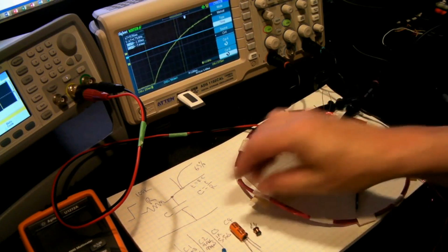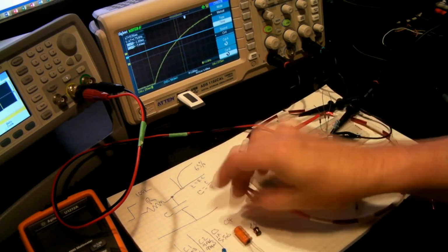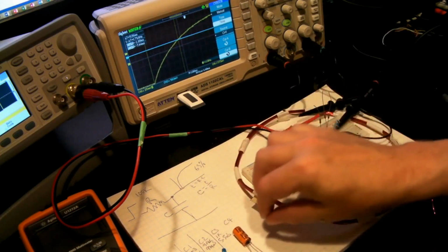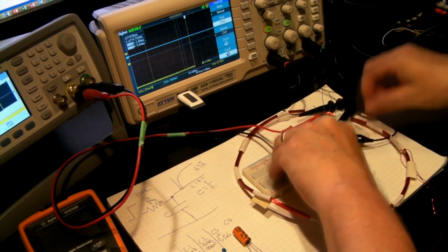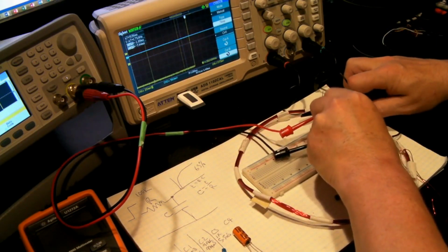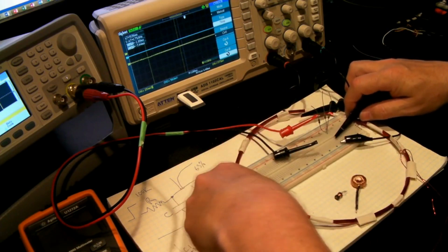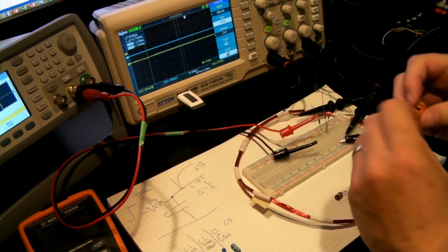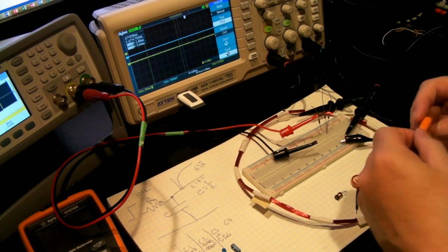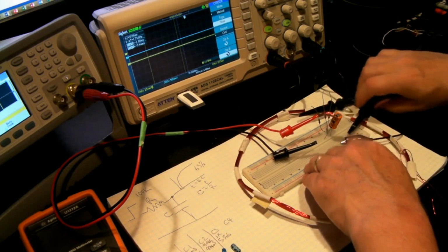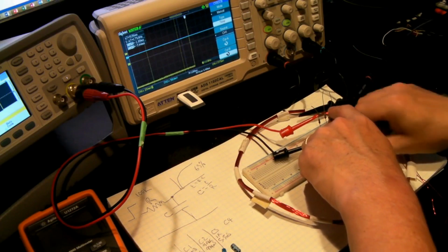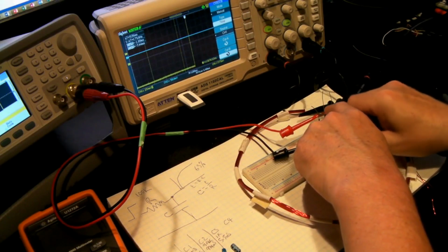So that's pretty good. Now the last one, C4 here, let me just get that inductor out of the way. We'll just quickly place this one on. I don't have a less than 1K resistor quite to hand right now, but that's fine. We'll be able to just slow the time base down to get a reading off of this. So this one's a 10 volt capacitor, so we're still going to be fine. Alright, going to connect the scope probe back in, connect the ground to the negative,